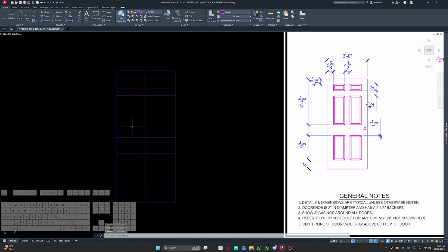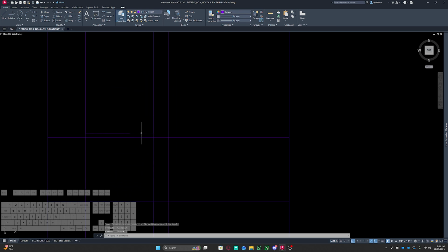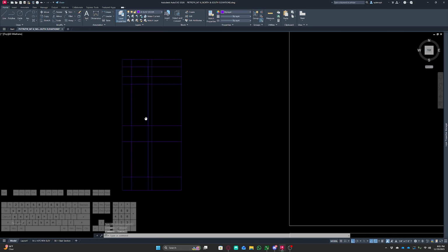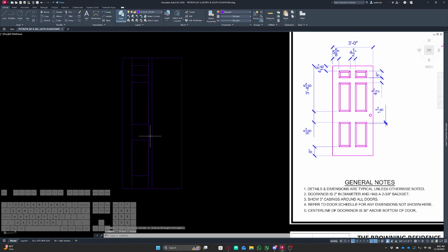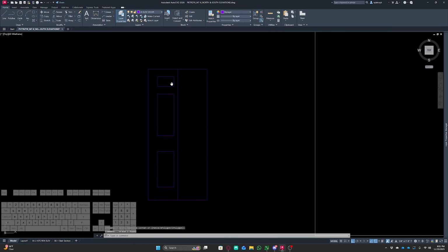That's looking pretty good. I can kind of see very visibly my panels. I'm going to offset in by 5 5/8. And I need to offset by 4.5. However, my center line's in the middle of that, so I have to divide it by 2. It's going to be 2 1/4. And I'm going to do something that I hope you follow. I'm just going to grab my rectangle tool and then trace out where these will end up going. I can clearly say I missed a piece. Bring that down. And I'm going to delete all of these guidelines I just created.